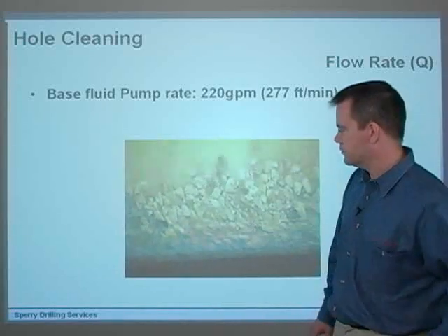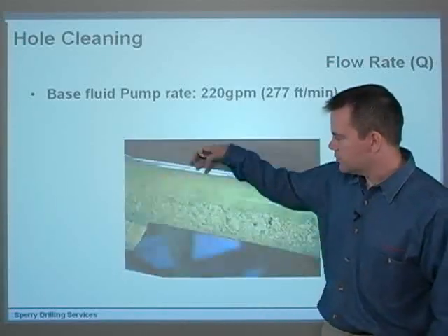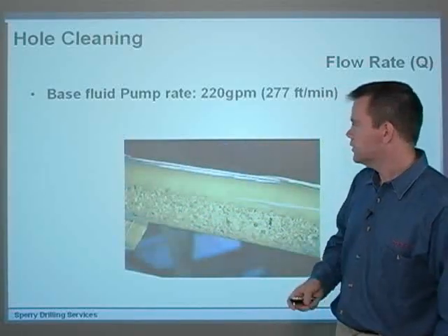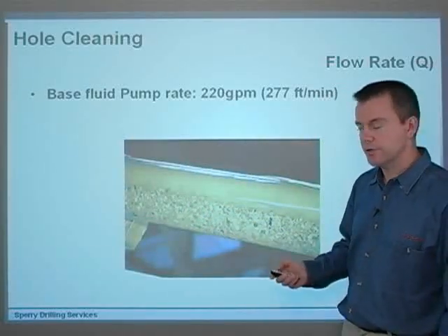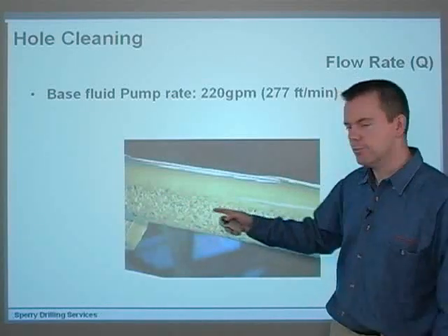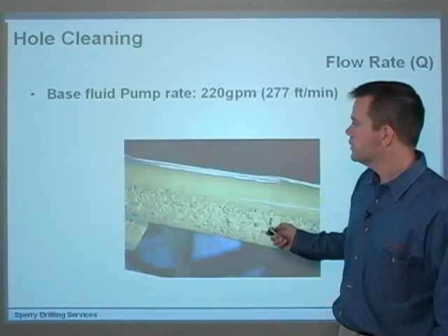It's still relatively thick. I mean, we're getting in there through the bed porosity, getting quite a bit more in the way of cuttings coming out at 220 gallons per minute. Still not enough though. It would still give you a heck of a lot of torque and drag in a wellbore that was as unclean as this.